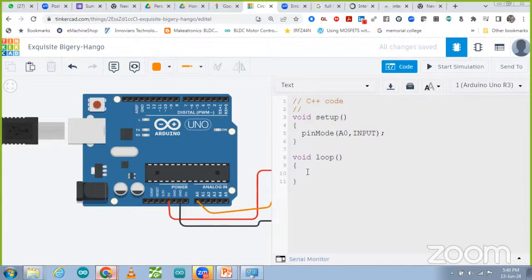Then after that you can use over here the condition. So we are going to take one global variable. We are taking it as int sensorValue, sensor or LDR value, you can call it LDRValue. Let me take V capital. Yes, LDRValue. This one is a global variable, and we can store value over there.